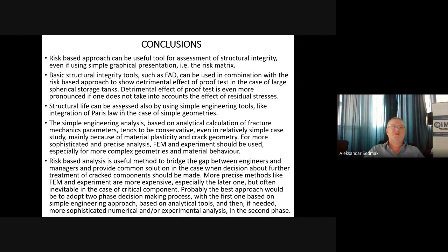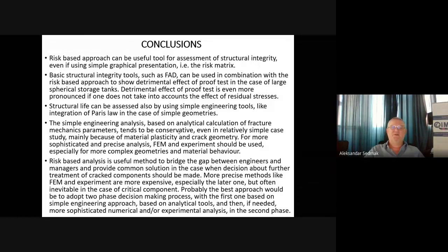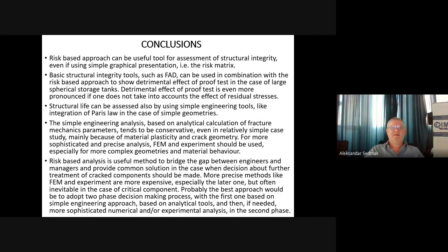Then that for structural life, we can use Paris law in case of simple geometries. That analytical calculation tend to be conservative, even in simple cases. So from time to time, we should definitely use either numerical or experimental method to verify our analytical procedures.